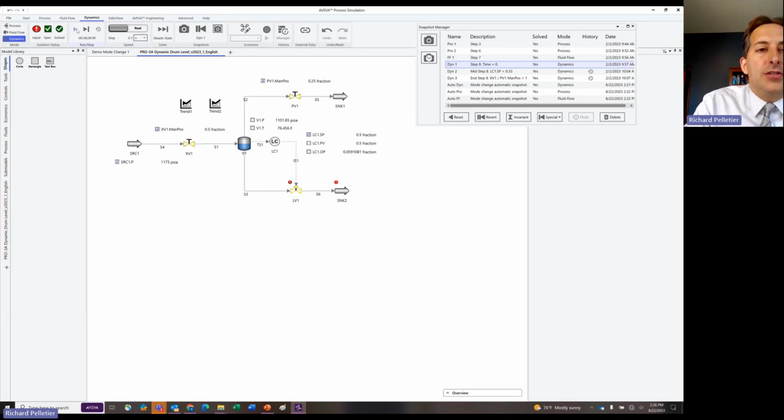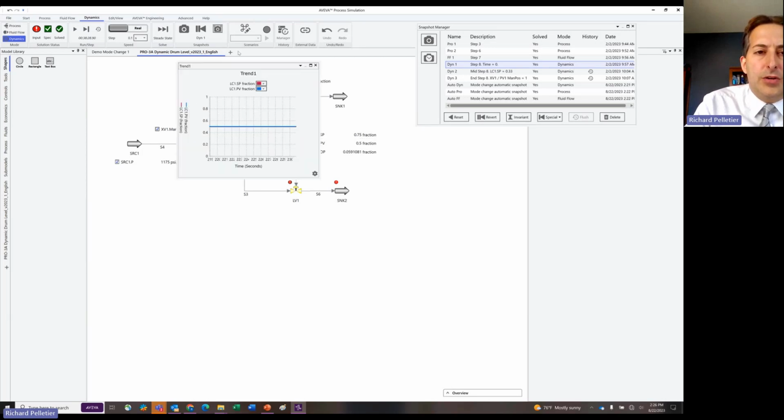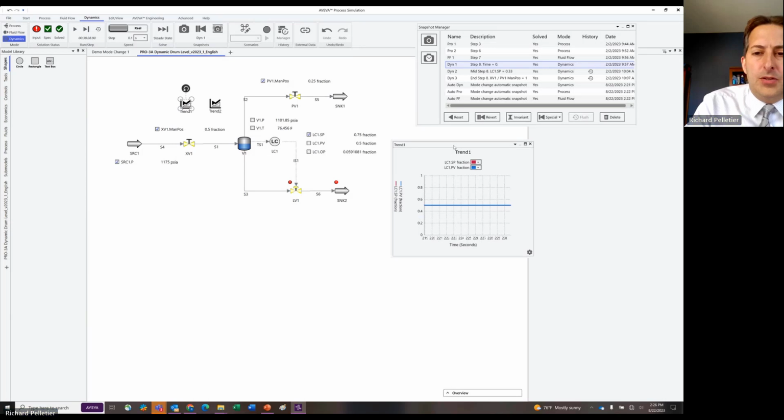All right, another thing that you can do is you can solve to a steady state. All right, so let's make a change real quick. 75. Let's open up this trend here. We're going to talk about trends too in a little bit. So you'll see I'll set one of these up. Now, when I start to run this, you can see information changing here, right? And so the simulation is trying to run to achieve a new steady state. So this is trying to get to a point where it's matching this, right? And you basically want to get to a point where all these values stop changing.